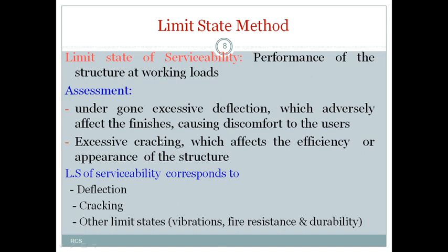And excessive cracking in a member or a structure will lead to inefficiency of the structure and it looks very awkward. The limit state of serviceability corresponds to the following parameters, that is deflection, cracking and other limit states like vibration, fire resistance and durability. So we have to check all those things while designing the members by using the limit state method.